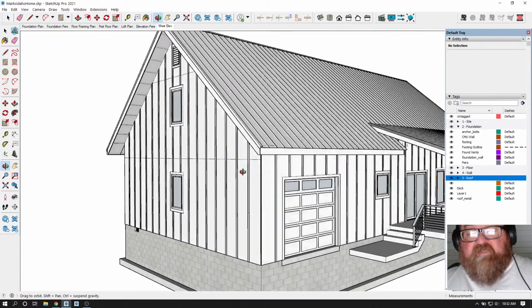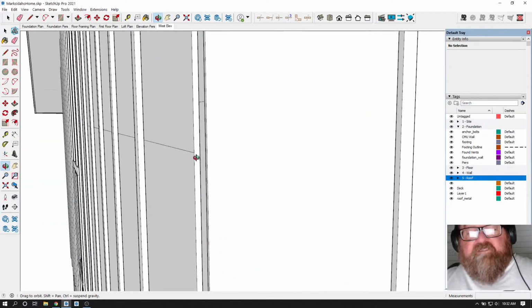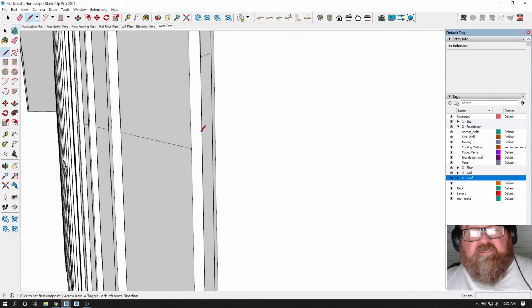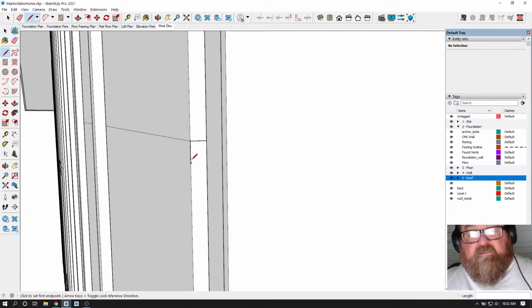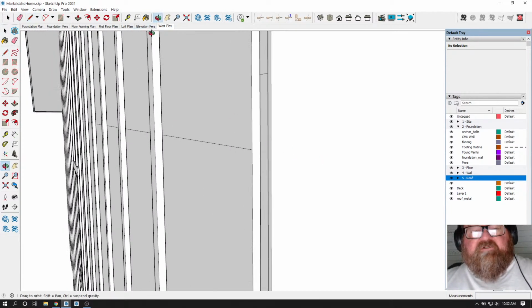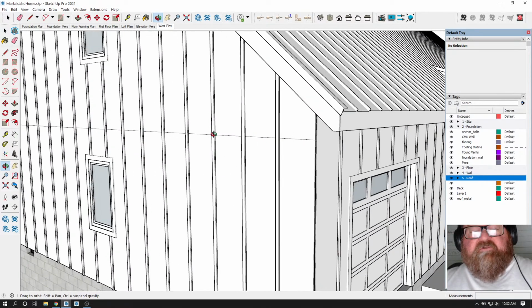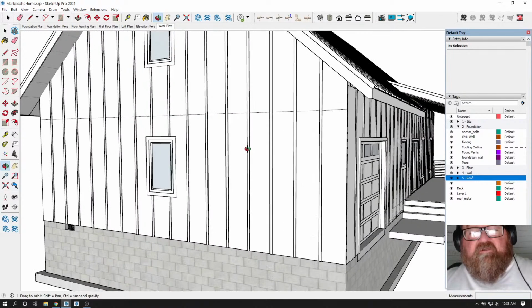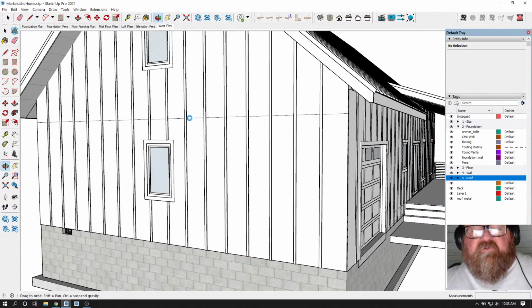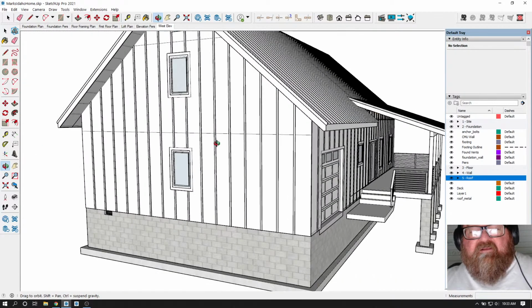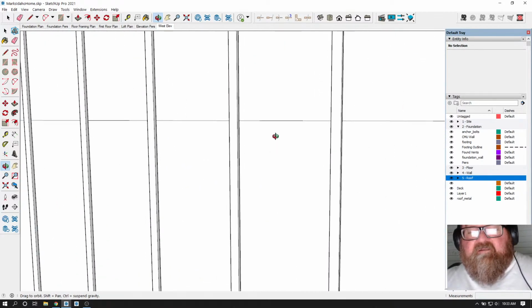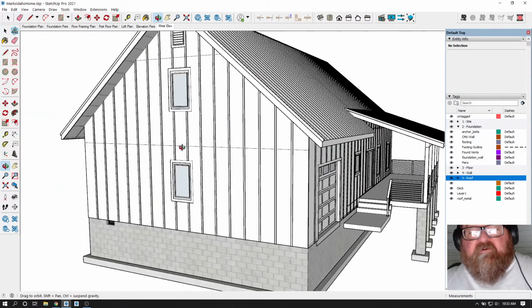And what the little Z flashing looks like is a flashing that comes up an inch, comes down and over and then down again, and it sits out over the face. Now I'm not going to show that thickness across there, because it makes the drawing look thicker than in real life. These are the little tricks you learn in drafting or architecture. When we print this drawing, that line will look like it's a half inch thick. If I drew it a half inch wide, the line would look really thick and bulky across there.